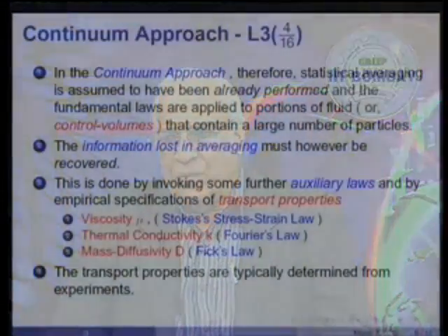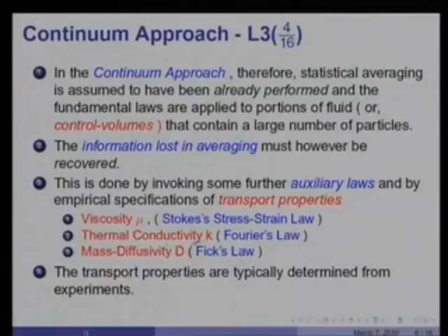Fourier's law of heat conduction, which is familiar to you, defines the thermal conductivity K, and Fick's law of mass diffusion defines the mass diffusivity. And you will recall in my first lecture I said all these are molecular phenomena. Essentially, they are molecular simply because they represent the lost information as a result of averaging at the molecular level.